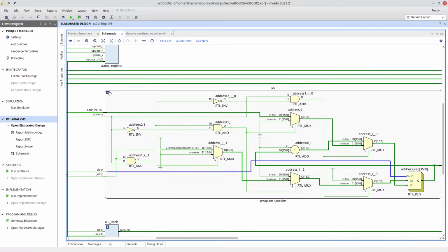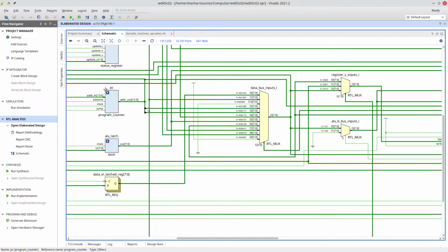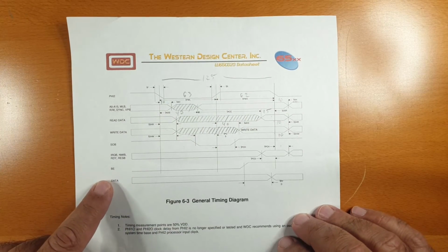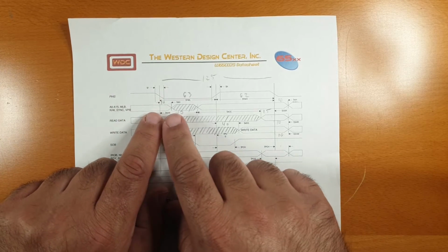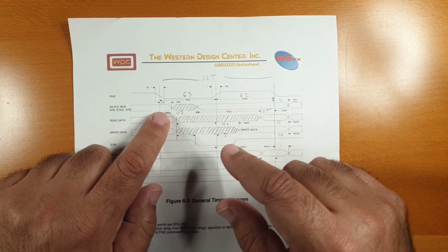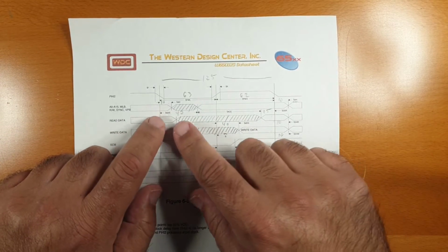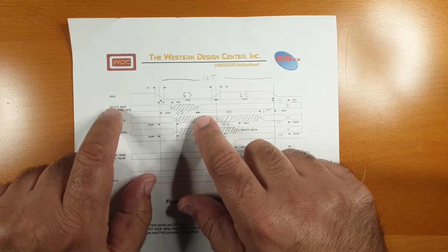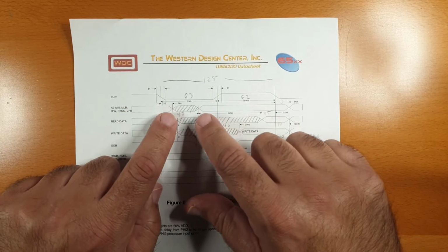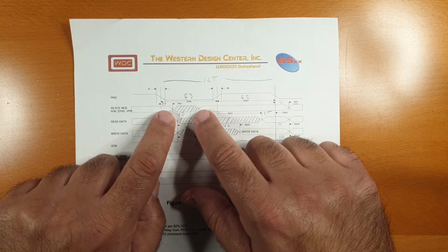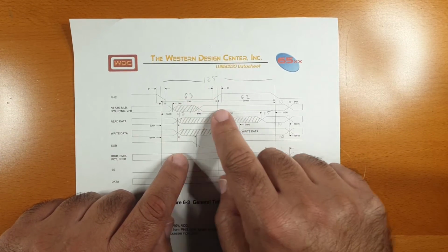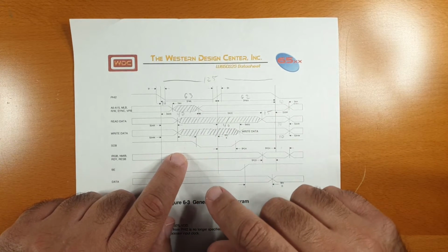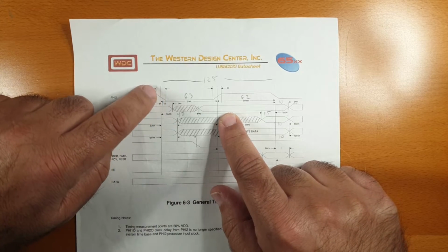To understand why, we first need to remember two videos ago where we analyzed the timing diagram and the schematics for the 6502 and came to the conclusion that we cannot latch both the inputs and the outputs of our design. This is corroborated by the timing diagram of the 6502 itself, where we see that past the falling edge of the clock, we have a certain hold time, which for the specific voltage we've been analyzing, 3.3 volts, is 10 nanoseconds. And then there's the address setup time, which is 40 nanoseconds. So we are allowed 30 nanoseconds to have invalid values on the address bus. The purpose of these invalid values is to allow us to use asynchronous logic and give it time to settle before the correct address appears. Even so, you will notice that the address line follows the falling edge of the clock.